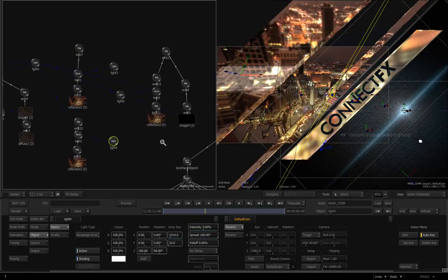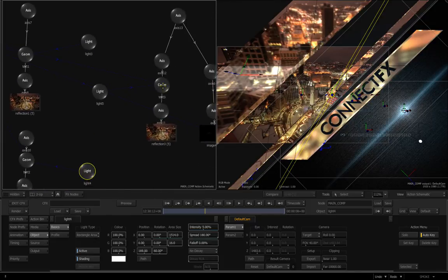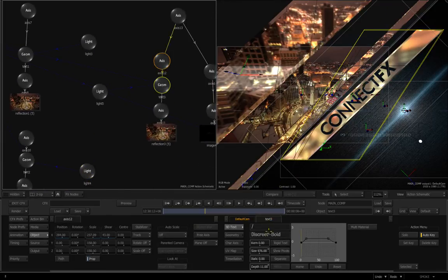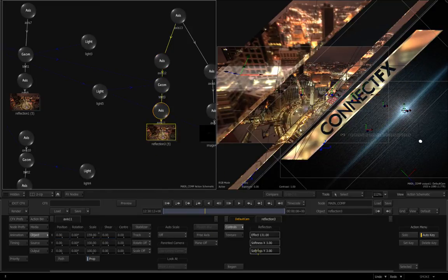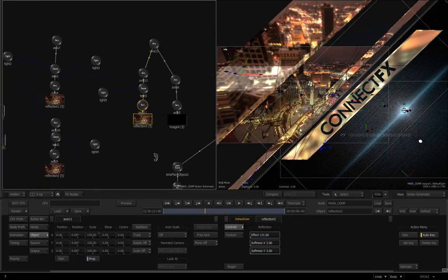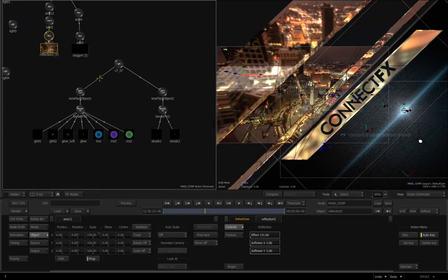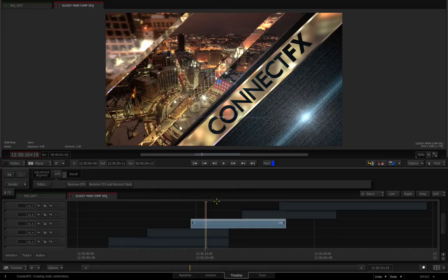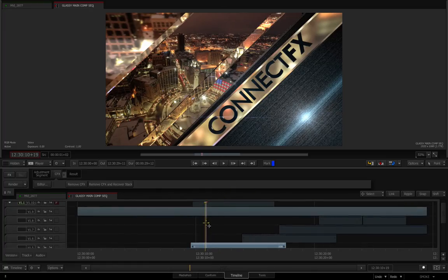This bar that the text is sitting on is just another forward slash of the same font. The reflection map here is softened and blurred with a value of 3. There's also a lens flare added into this scene. So going back to the timeline, the rest of these effects are sort of built using the basis of the ones we've already looked at.